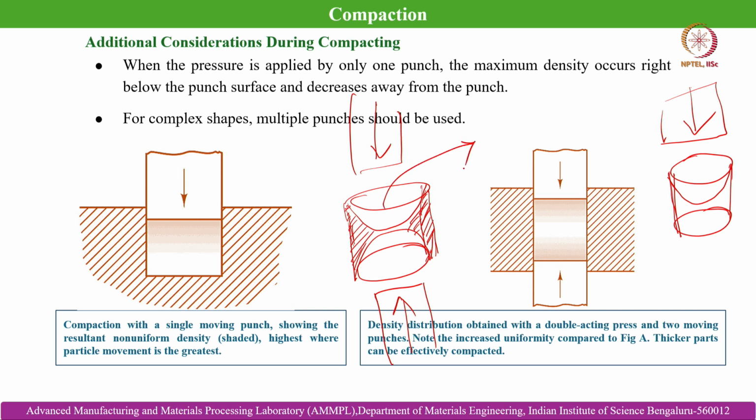So, the end result after sintering is that this part will show dumbbell shaped attributes because of the differential shrinkage at different locations along the powder aggregate. So, what are the remedies to overcome this defect or this difficulty? We will learn about that later.